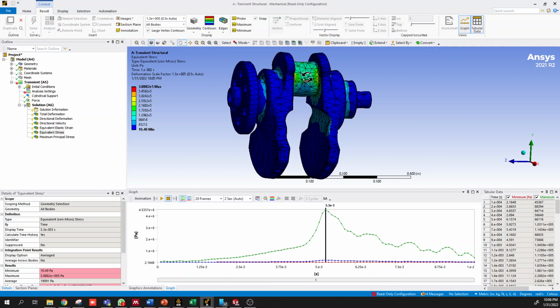The force application worked. Then you added the rotation and the model didn't converge. So it's easier to troubleshoot when you apply that type of process flow mentality to your simulation building.